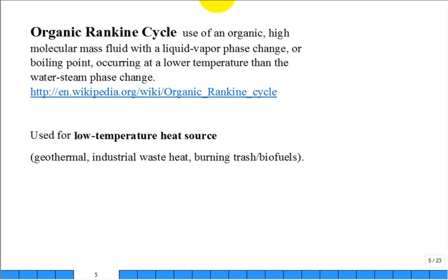Well, you'll see the kicking around of this organic Rankine cycle. Basically, it's still the major components of a boiler, turbine, condenser, pump, part of the Rankine cycle, and you can have enhancements to it like superheating, reheat, and feed water heaters. But this word organic means that you're basically using an organic molecule, typically high molar mass molecular fluids. You say, what does this word organic mean? It has some carbon in it. Does water have carbon in it? Is water an organic? No, it's not.